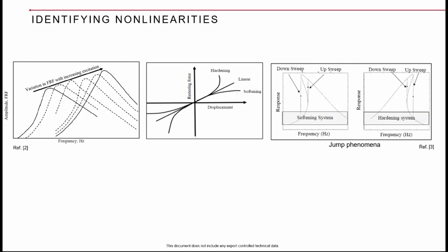So in these kinds of situations, like I already pointed out, you can always come up with a regression analysis and develop an equation. You can develop a transfer function between your natural frequency or the additional stiffness that you want to model as a function of excitation levels. Okay, so as the excitation level changes, between the two components that are interfacing, you can model the stiffness as a function of the excitation frequency, so that you can always predict the behavior well ahead. So that is where I'm trying to say that the data driven approach works.